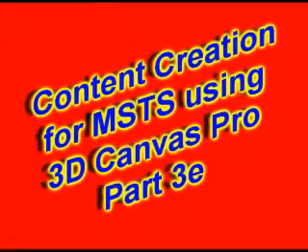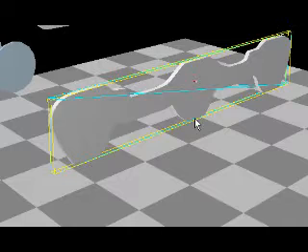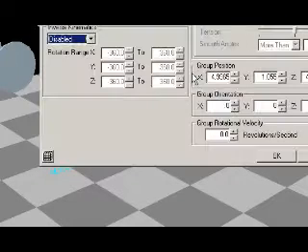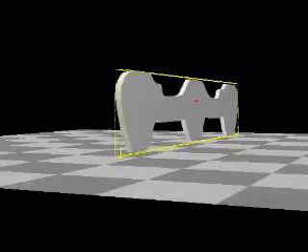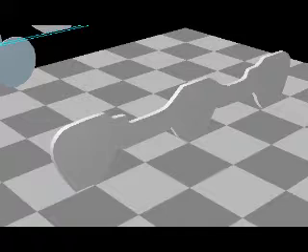Based on the height of this bogie frame and the height that the bottom of it is off the ground, the position in the y-axis should be 0.7125. So I'm just going to add that in now. And it actually looks pretty good, so we'll do that to the other one. I'll bring it over so you can see.